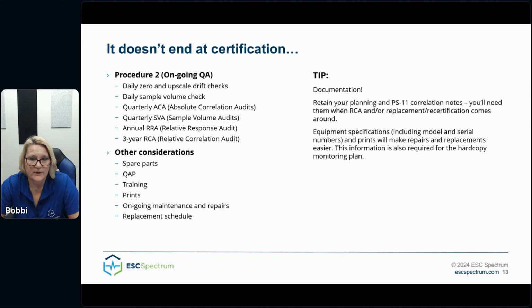This will require elevating your PM levels as you did during the initial correlation, through detuning or fly ash reinjection, which can be difficult on short notice. So have a backup RCA plan ready. You may even want to check the availability of the necessary resources in case they're needed on that short notice.